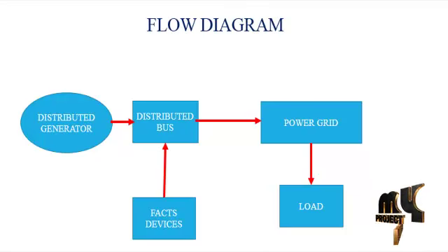TCVR is considered a common voltage regulator. It is able to smoothly vary voltage magnitude with tap changing in the control range. The tap ratio is connected in series with the impedance of the distribution line. The TCVR operates by inserting an in-phase voltage to the main bus voltage so as to change its magnitude. It is modeled by an ideal tap changing transformer in series with the branch. Its value depends on the main bus voltage magnitude Vp of the line in which the device is located, and the additional voltage in the range.